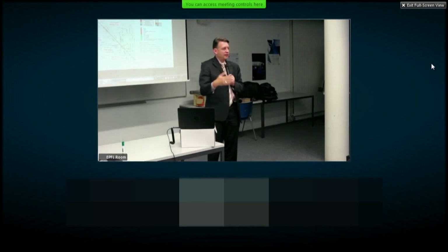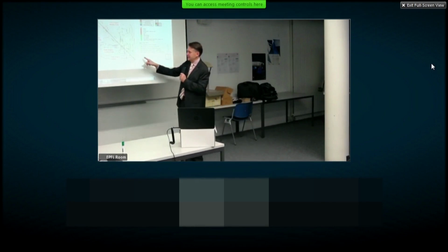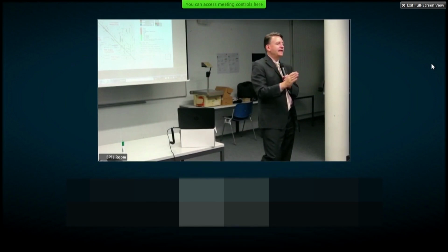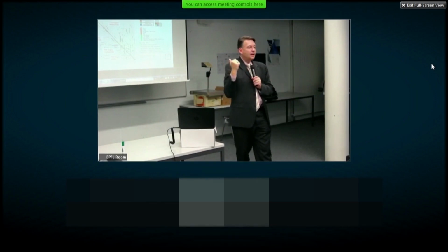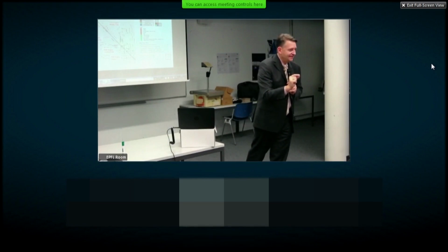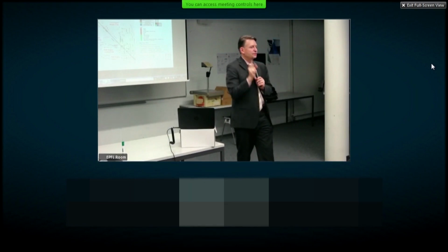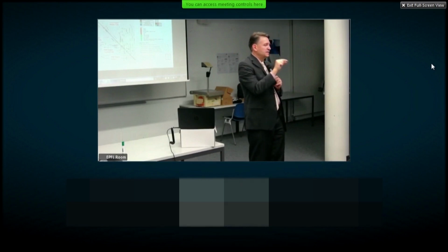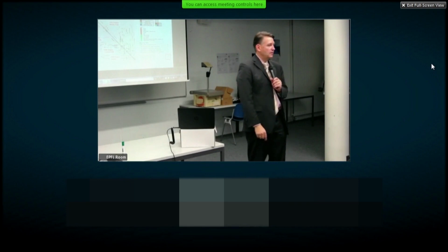we went through a process where all of these 84 teams, for their component, had to sign off and say, yep, you've accurately captured my interfaces. My physical, mass, information, and energy interfaces have been correctly captured in this matrix. And, oh, by the way, the empty cells have also been certified. So if there's an empty cell here, there's no question whether maybe somebody just forgot to put the interface there. No. The owner of that row and column certified that there is no direct interface between this component and the other component. That's why it took 31 versions.